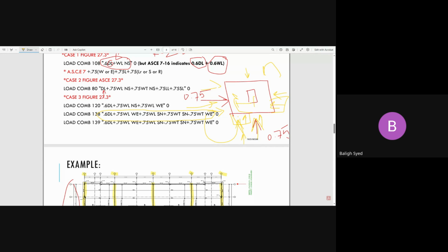I'll send you the whole thing, either in an Excel sheet or in text form: all the load combinations, when you're going to add and when you're going to subtract. So you can see that in the next load combo we are considering the worst load combos when you apply them on the structure, especially for utility structures, industrial structures, or low-rise, mid-rise and high-rise buildings: 0.75 wind in west-east, 0.75 wind in south-north. So actually you combine both of them, from both directions, which are orthogonal or perpendicular to each other. Then you add the wind torque. One time you're adding and one time you're subtracting.